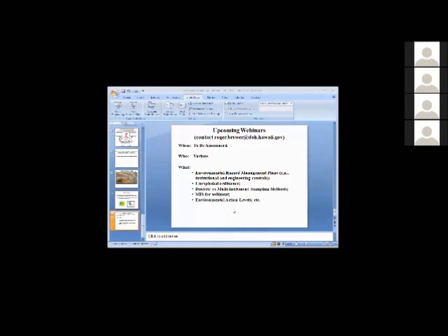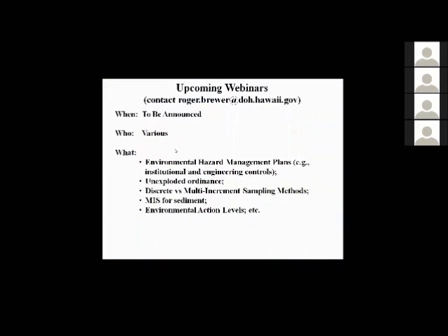And Mort, this is Roger. I ran those numbers. Now I assumed a 20% porosity and a thickness of fill material under the slab of 15 centimeters, and I come up with about a 25 centimeter radius of influence. Just for comparison, a 100-liter sub-slab soil gas sample comes out to about a 100 centimeter radius of influence. And for the first person who can figure out how to get a 100-liter sub-slab soil gas sample, I'll buy them a beer at Duke's in Waikiki.